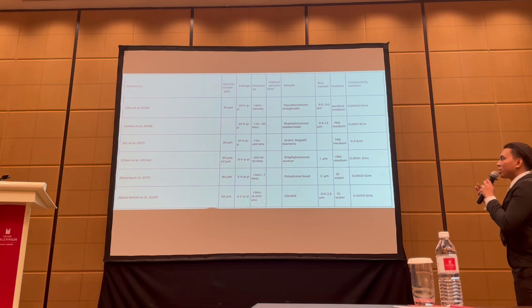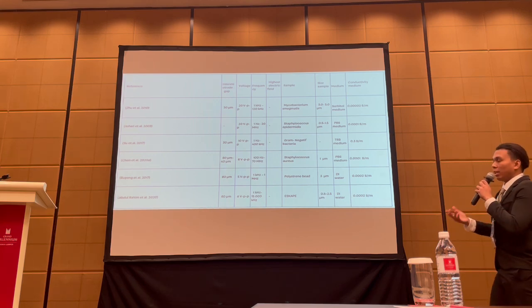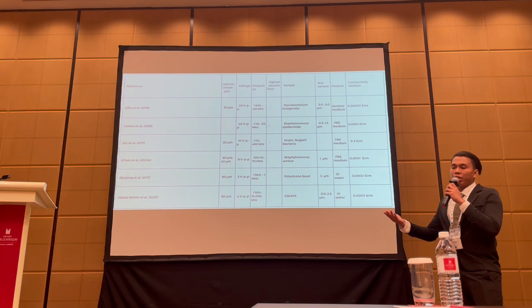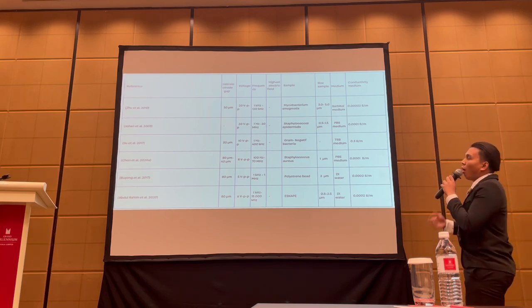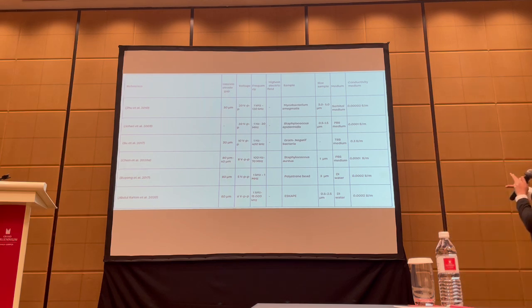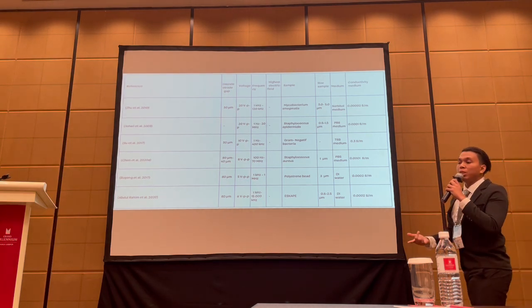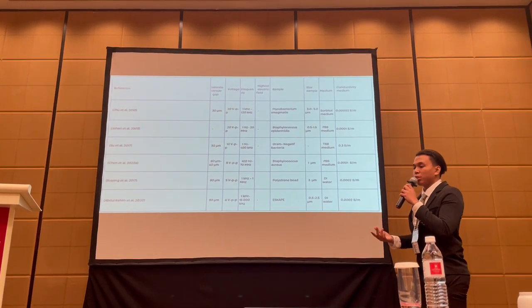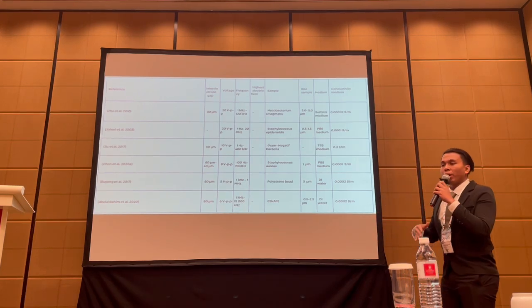We need to keep constant the medium and also the inter-electrode gap, which doesn't affect the DEP response, but affects the electric field of every experiment. So based on this past DEP research, we decided to use DI water, which is easily accessible and can be used for every biological particle. Dilution factor of distilled water can be applied to any sample.